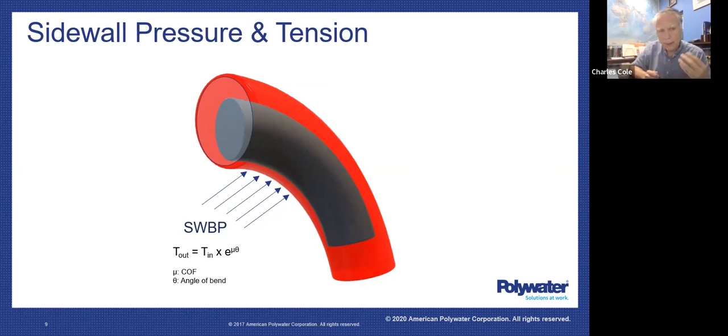So that's why I mentioned before that one of the issues that you might often encounter in installing cable and duct would be the inappropriate design of a duct run, either radii too small, or you've got frequent bends and things like that. And one way of taking care of those issues in that exponential buildup of friction, and therefore tension, can be resolved by lubricants. Let's take a look at some examples of what I'm talking about here. So if you can go to the next slide.